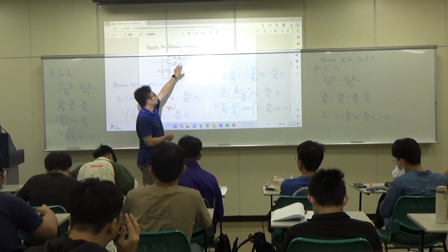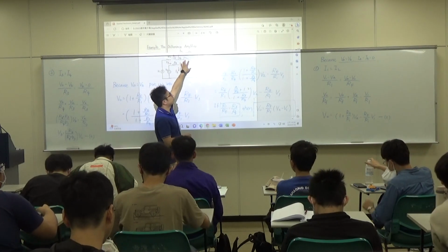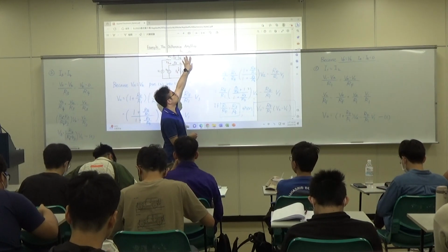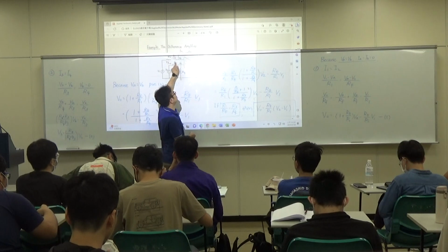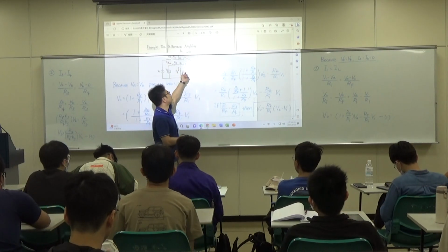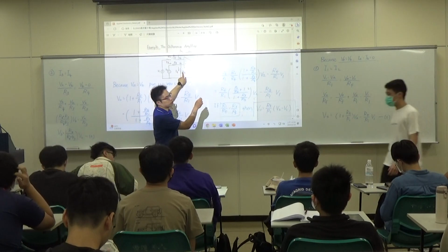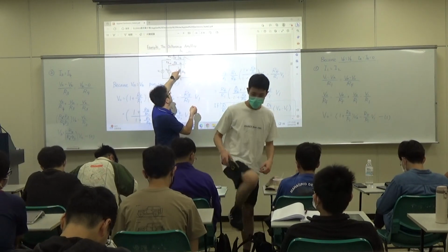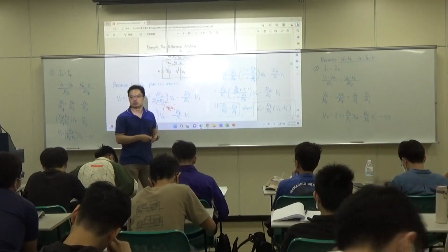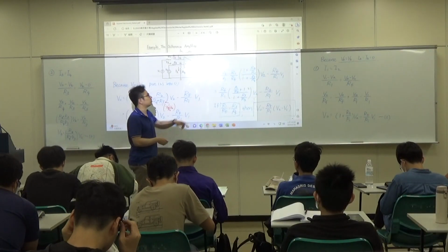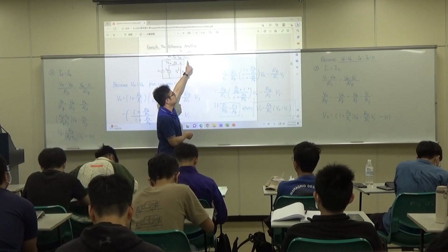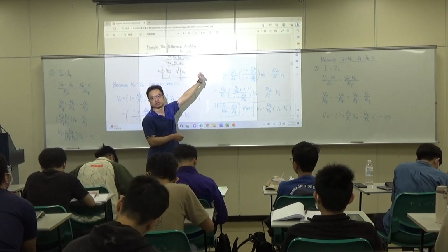So the operational amplifier remains the same. We don't need to change anything about this. We just need to change the values of resistance. So we often use a variable adjustable resistance at certain place, and then we can change the gain. We call it closed loop gain because it is always operating in a closed loop configuration.